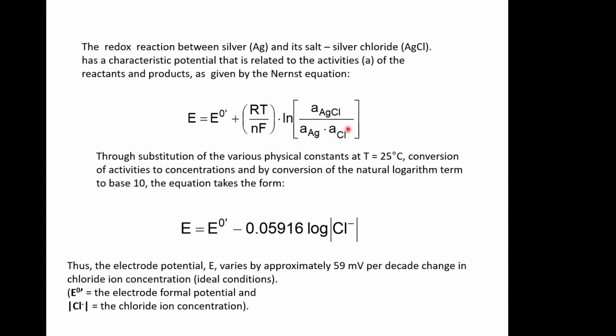And so if you change the concentration of chloride, which is the thing we're interested in, it changes the ratio of this log function, which eventually changes the voltage that's being generated on the sensor, and these are all hopefully constants. So maybe you didn't think GCSE chemistry was going to be of any use to you, but actually it turns out that there's a lot of chemistry in electronics anyway, because fundamentally chemistry is just a movement of electrons. These are just ions down here.